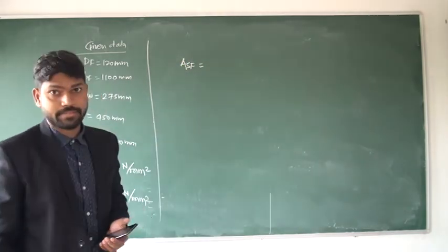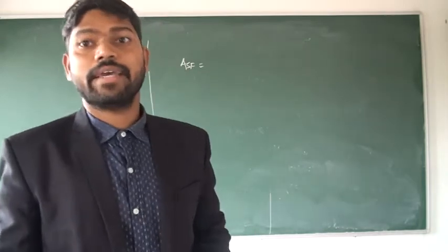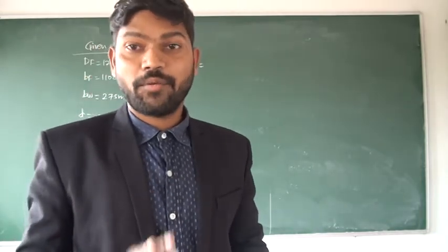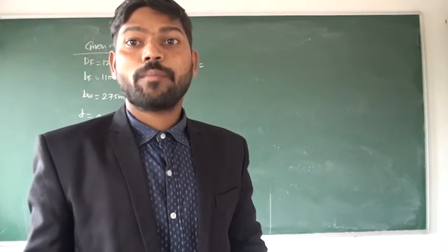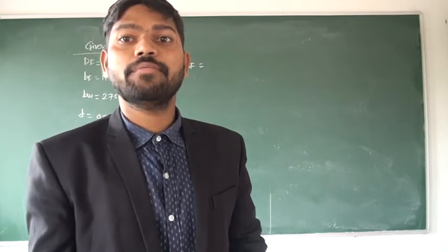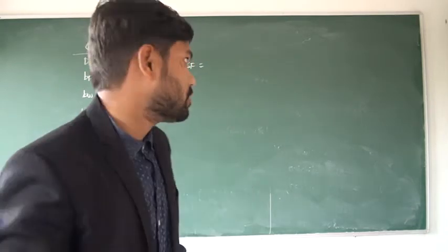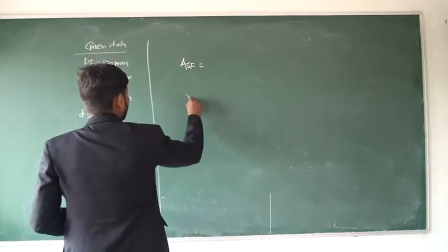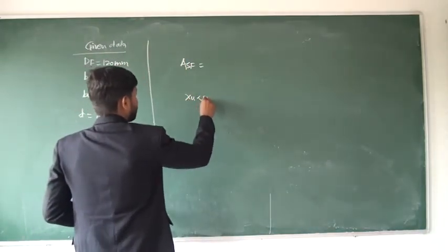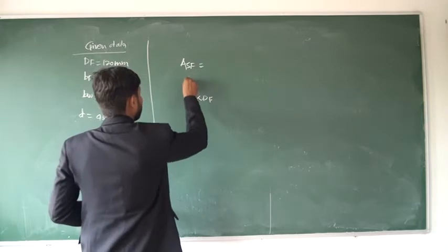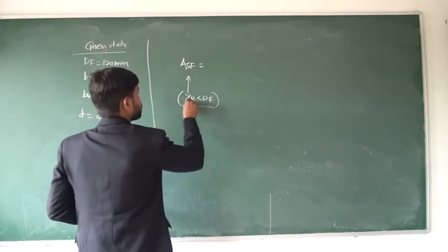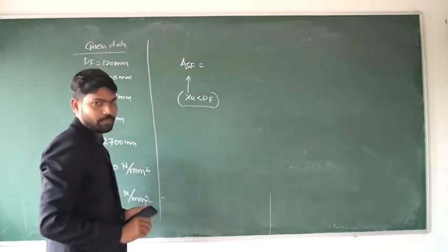What is ASF? ASF is the area of steel required for compression to be within the flange. Compression to be within the flange means XU value less than df. ASF required for XU value less than df.